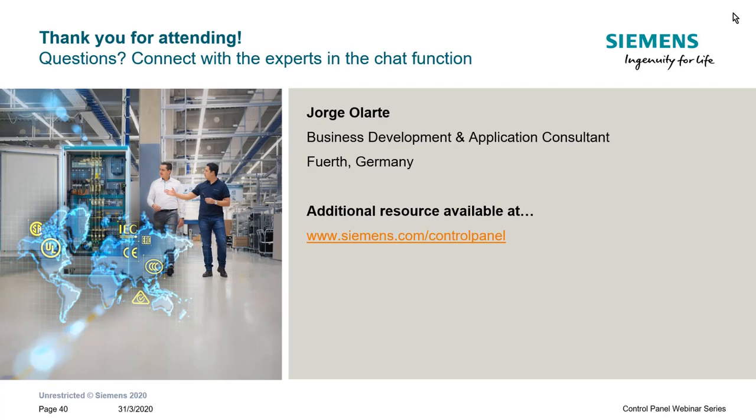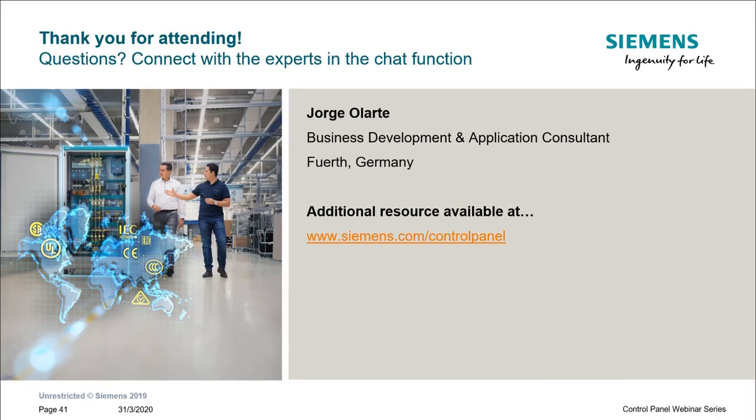Depending whether or not you need selectivity or backup protection, this will also influence your costs a lot, but this all comes in the design and in the engineering, and it will all depend basically on the short circuit calculation. This type of decisions you will make here. Please remember this and always use, when you can, the SIMARIS Design tools.